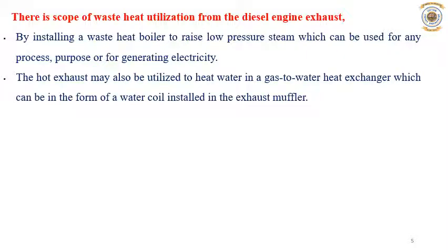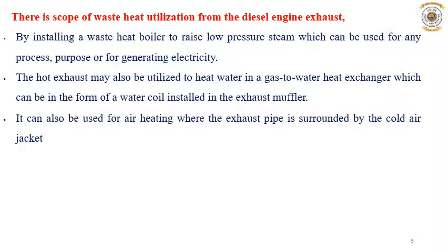The hot exhaust may also be utilized to heat water in a gas to water heat exchanger, which can be in the form of a water coil installed in the exhaust muffler, or we can use this waste heat for heating air, where the exhaust pipe is surrounded by a cold air jacket.